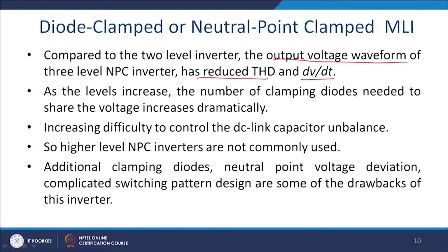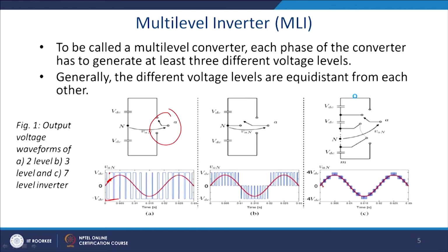So, let us understand what happened there. We have shown the case here. So, this is basically the multi-level inverter. Since this capacitor voltage is not actively controlled, the current coming into the system and going out will basically give the status of the amount of charge, and that will be reflected as the voltage available at the DC link.